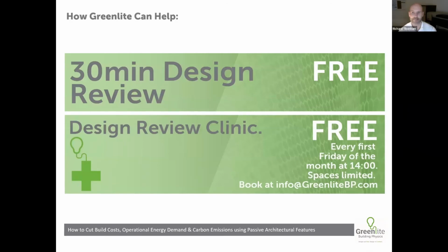So how Greenlite can help with these aspects is we do offer a 30-minute free design review. We'll go through your project, we'll point out any obvious errors. We've literally done hundreds of projects, and we're wading through all this data in depth on a regular basis. So I've got a good understanding of how buildings perform theoretically. So we can use that knowledge to avoid some common pitfalls like large areas of west-facing glazing, for example. They can lead to overheating risks, and that's just one example.